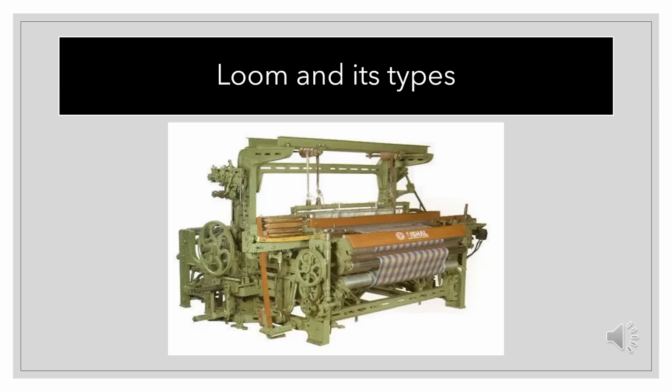A rapier machine may have a single rapier to carry the weft across the full width, or a single rapier operating bilaterally with a centrally located bilateral weft supply, or two rapiers operating from opposite sides of the machine. The rapier loom comes in many types. Early models use one long rapier device that travels along the width of the loom to carry the weft from one side to the other.